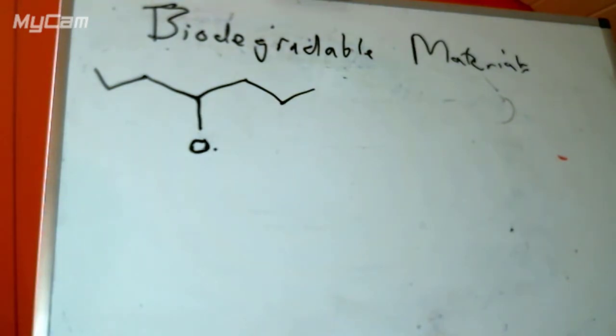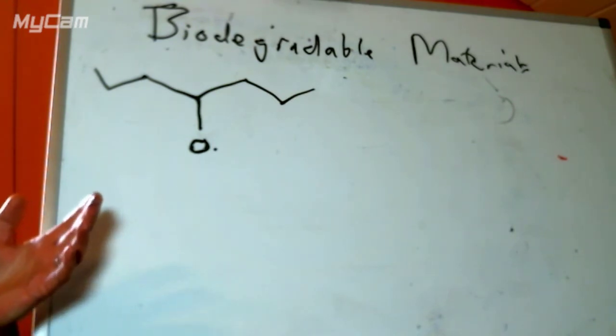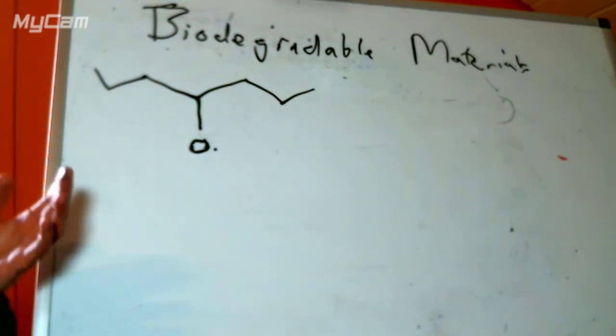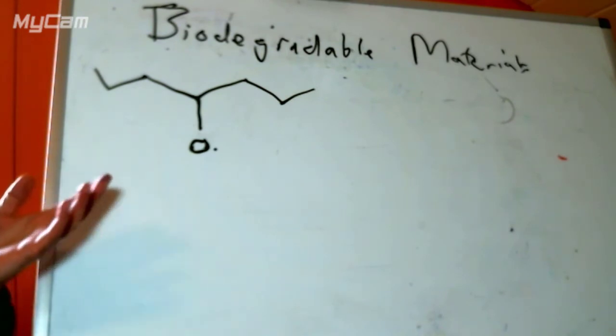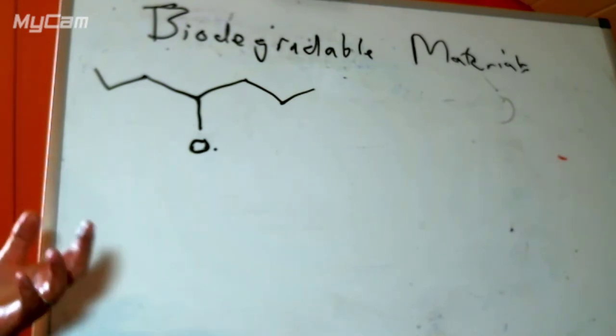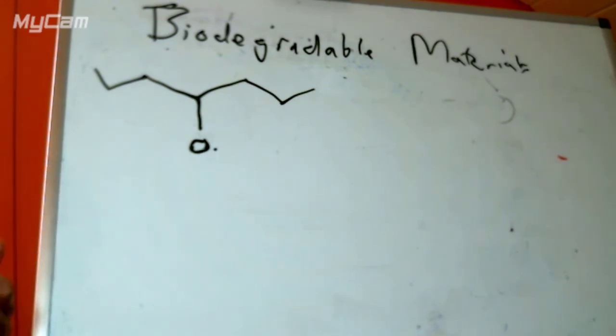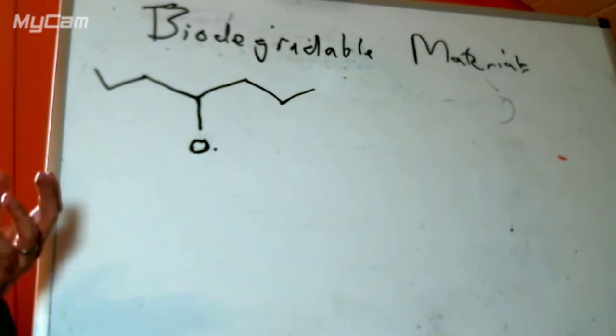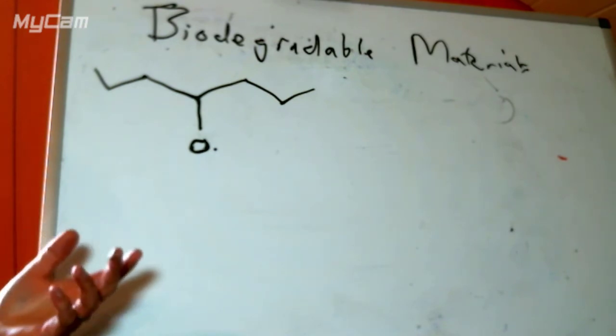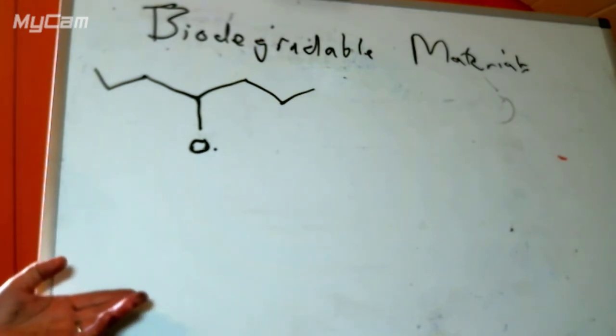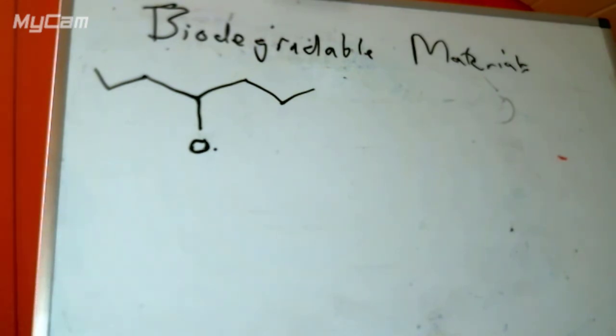So there are two critical things that I'm interested in here. One of them is that it's fairly normal inside polymers to vary the rate of reaction with oxygen. So a typical polythene bag, a typical polymer that we would carry around with us, would contain some kind of antioxidants to slow the reaction down, and they would have been affected in exactly the same way as our iron soap or our cobalt soap.